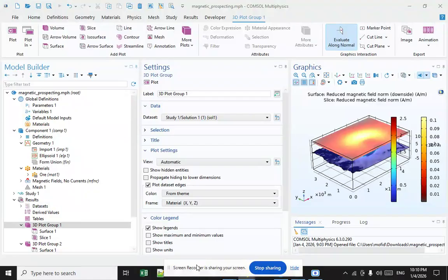The two main methods of recycling iron from iron ore tailing are magnetizing roasting and direct reduction. Magnetizing roasting uses temperatures between 700 and 900 degrees centigrade, which means 1290 and 1650 degrees Fahrenheit, for a time of under 1 hour to produce an iron concentrate, Fe3O4, to be used for iron smelting. For magnetizing roasting, it is important to have a reducing atmosphere to prevent oxidation and formation of Fe2O3 because it is harder to separate as it is less magnetic.